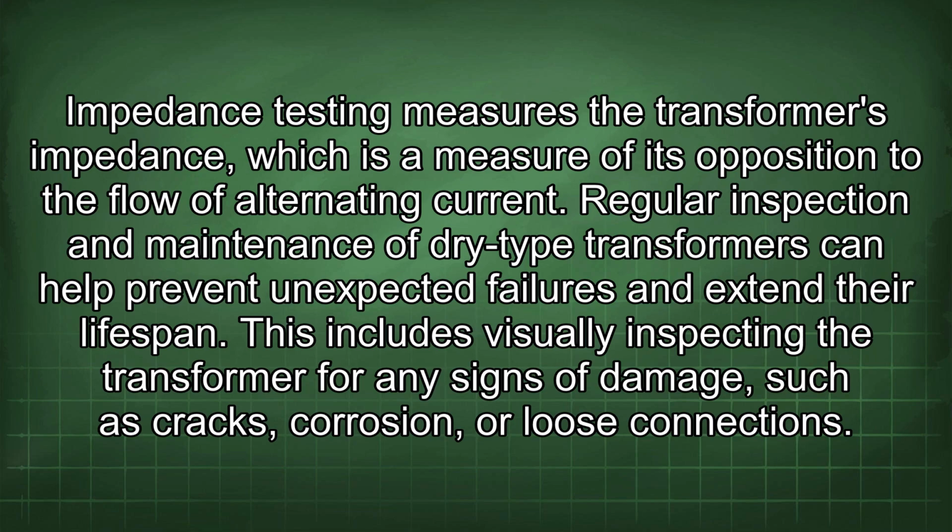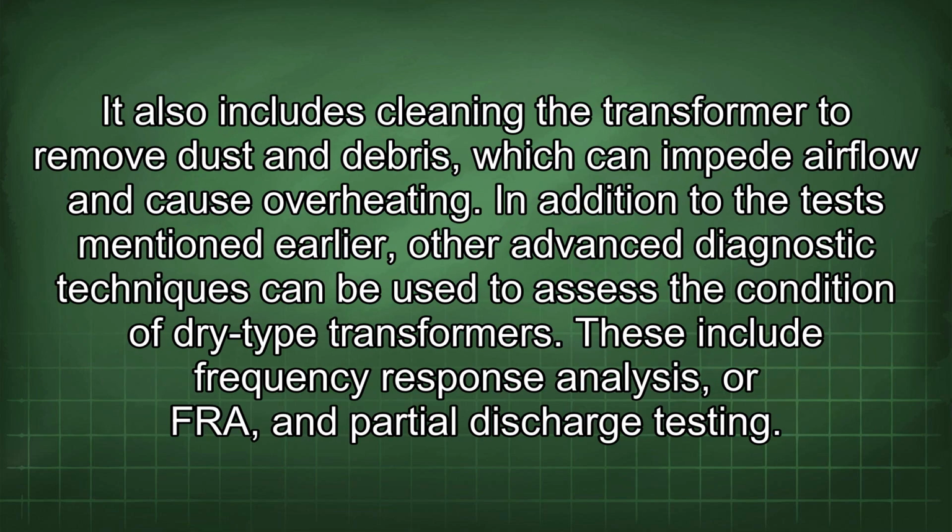This includes visually inspecting the transformer for any signs of damage such as cracks, corrosion, or loose connections. It also includes cleaning the transformer to remove dust and debris, which can impede airflow and cause overheating. In addition to the tests mentioned earlier, other advanced diagnostic techniques can be used to assess the condition of dry-type transformers. These include frequency response analysis, or FRA, and partial discharge testing.